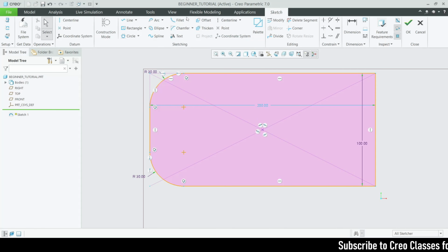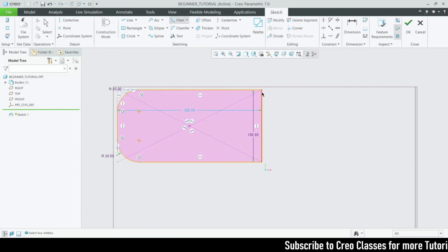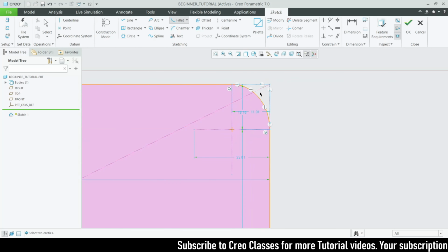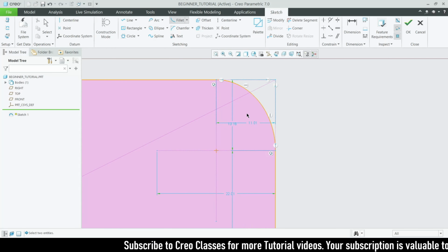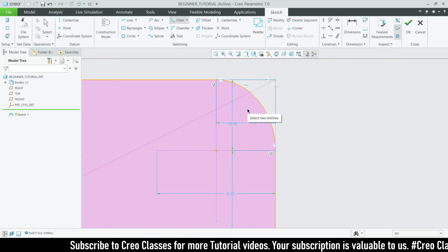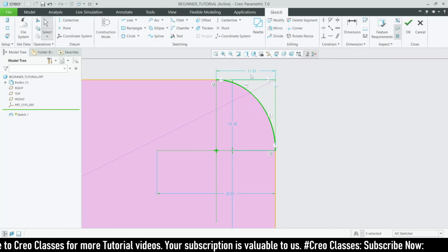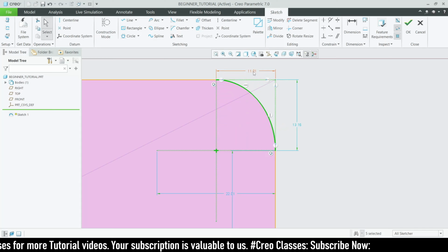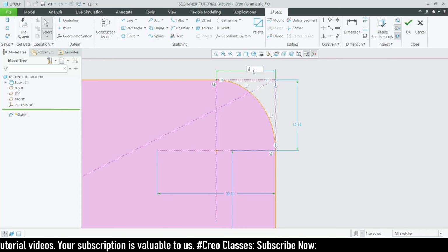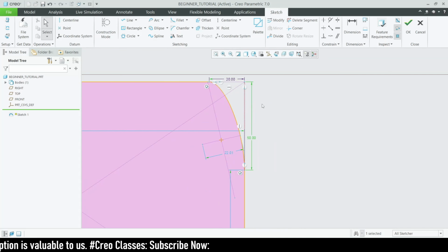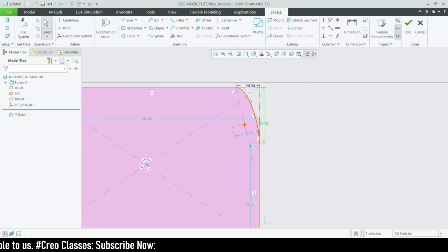And the same on the other end for the elliptical also. For circular trim, it will be taken as a rounded shape. For elliptical, it will look like an ellipse. In this we can't change the radius for that curve. Instead, we can change the distance for this ellipse. Here we can change it as 20, here as 50. As you can see, it is turned into an elliptical shape. So this is how it works.